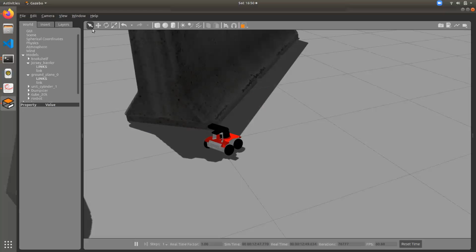So when you send the movement command, the cloud server acts as an intermediary to connect your ROS environment to the app. You send commands to the server and it stores and buffers them, and when the ROS node connects, it gets the commands from there and executes them on the robot. You can do something like that.